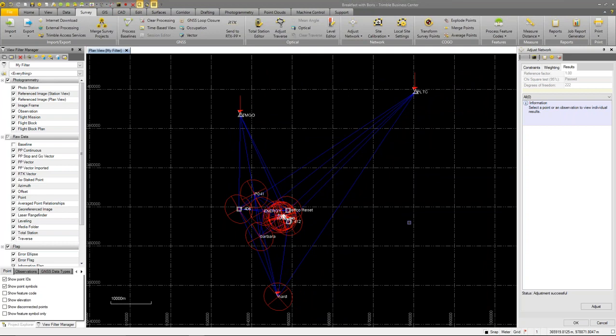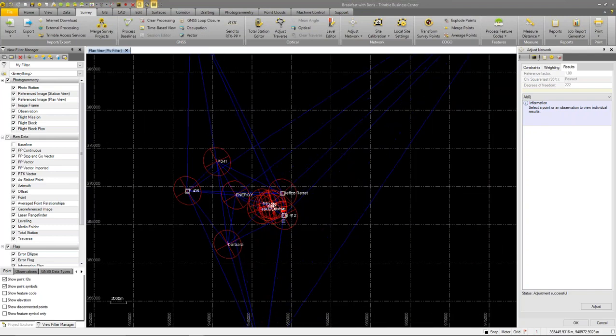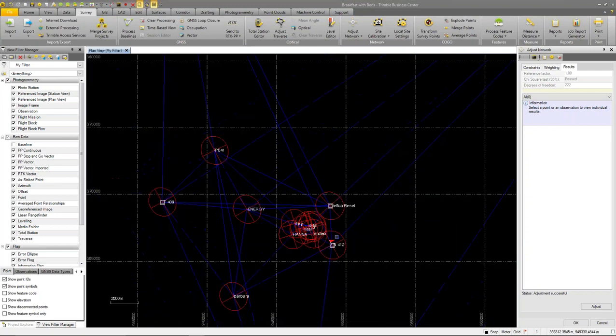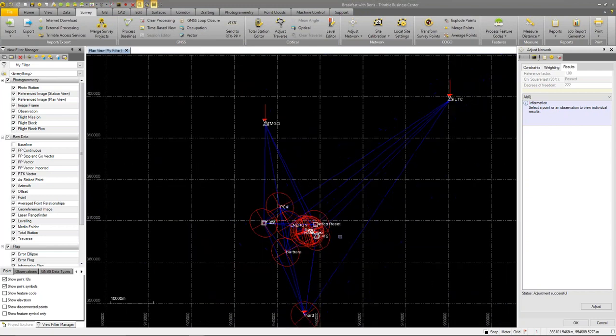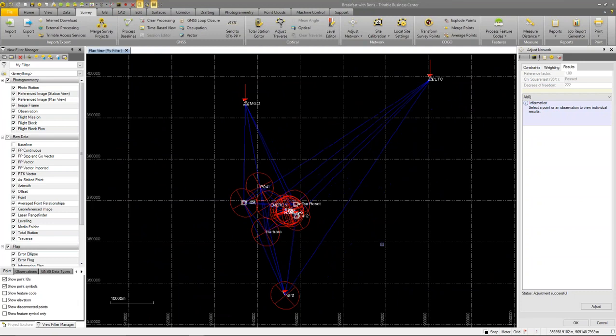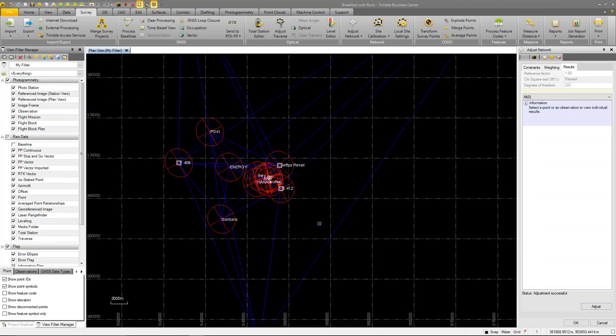If you have more than 1 point, I would try to use it if you trust the control and how well the control fits together that you're tying to. And if I really want to say that my coordinates are relative to the NGS network, I pretty much have to fix more than 1 point in order to do that, because the NGS network itself has some adjustment in it, and it's basically defining its own local datum here, right? And I need to rotate into that datum and scale to really fit with the local datum before I can make a statement about my coordinates fitting that datum. So I would fix more than one if it's possible. You have to fix what you can.